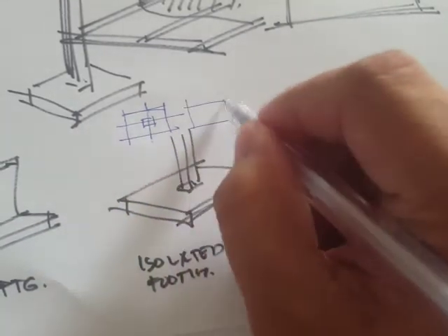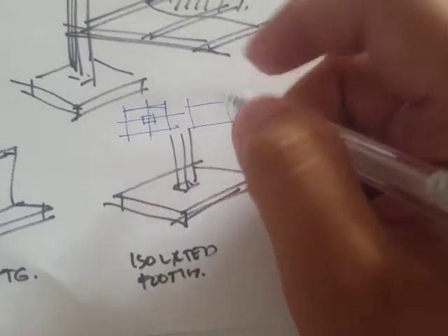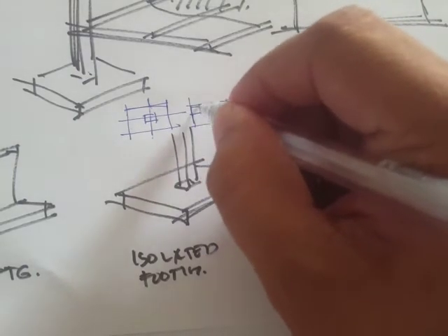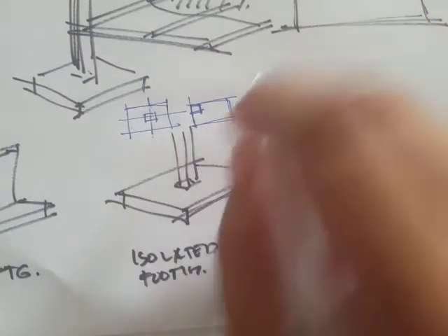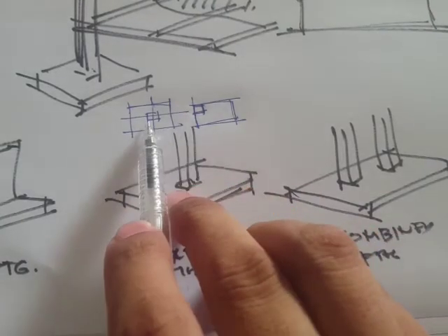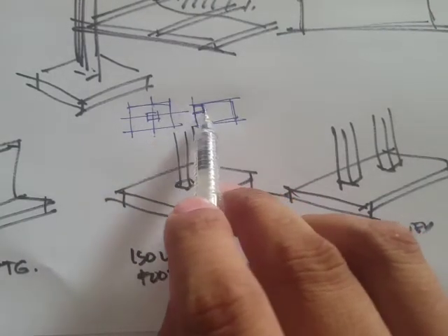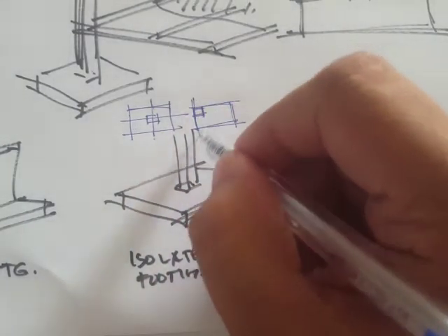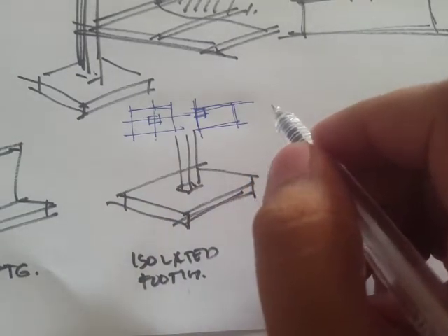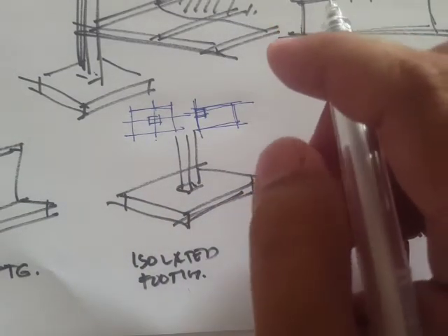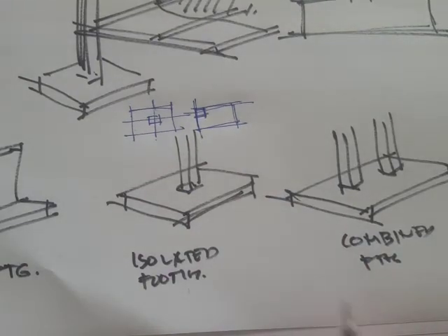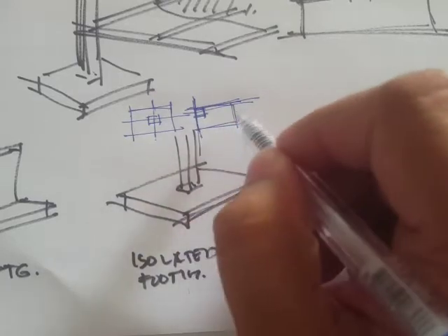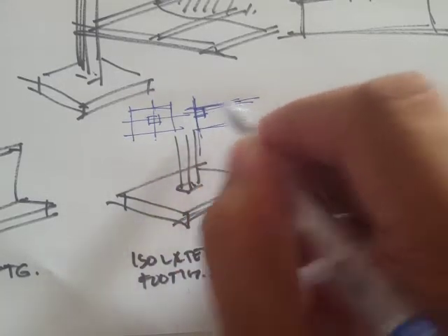It is also possible to have this footing wherein you have this configuration. Instead of being at the center or at the centroid, it is actually offset, or eccentric. This will be common for footings along the property lines, meaning that you cannot extend anymore, so you have to design the footings in this manner.